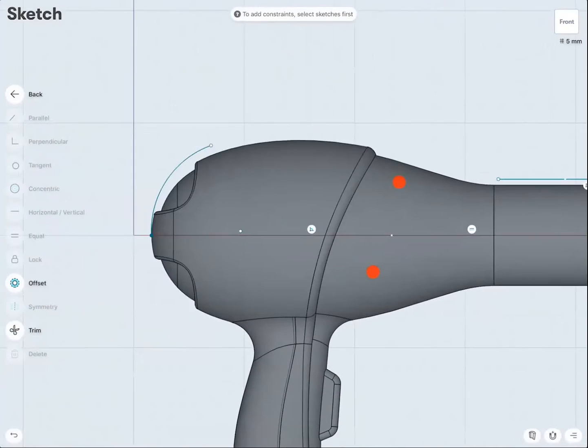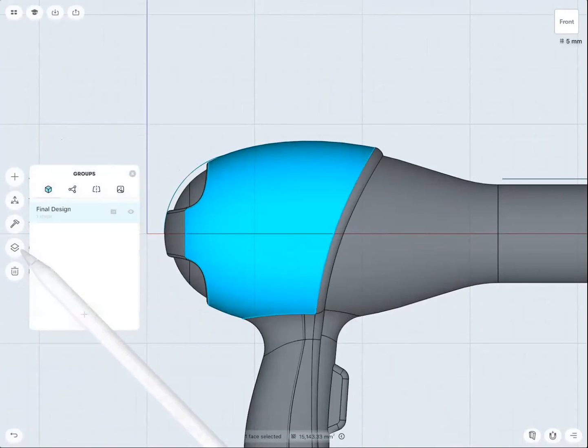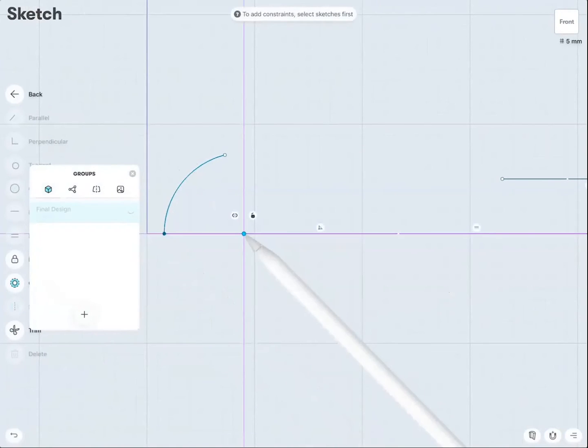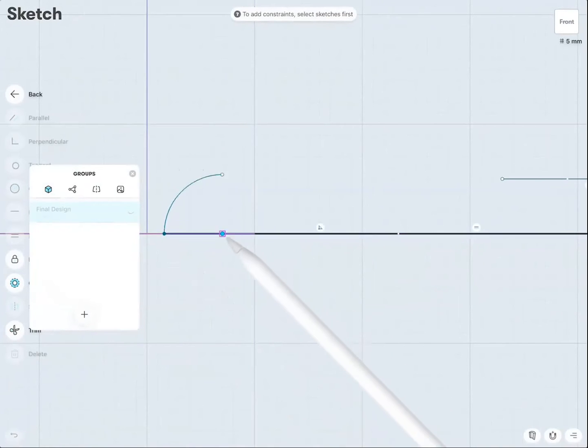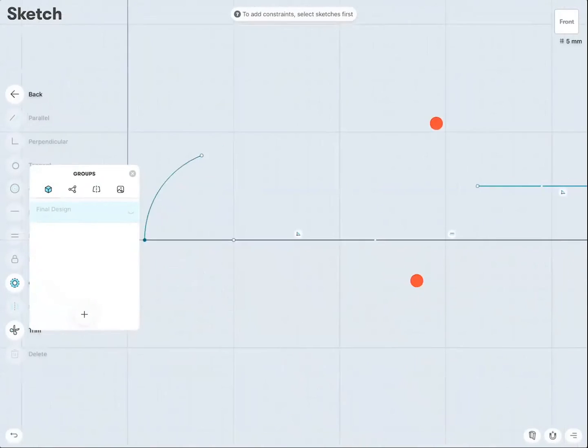So now I would like to create the spline that goes in between. And I just saw that this actually moved away. So I will maybe hide this one for the moment. I have to probably just snap this one by hand. No, I did it. Maybe the geometry was a little bit in the way. You see, to the left of the lock, there is the coincident constraint, which makes sure that this point only slides on this line and it can't go up and down anymore. Good.